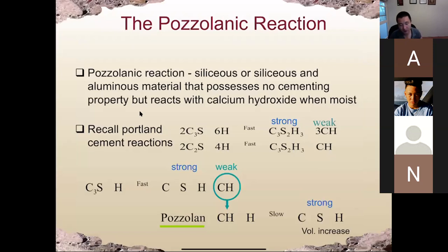And here shows the pozzolanic reaction, which is coming from previous classes. Okay. So calcium C3S or C2S together with water, and we generate CSH plus calcium hydroxide. And we know CSH is stronger and also insoluble compared with calcium hydroxide, which is weaker.